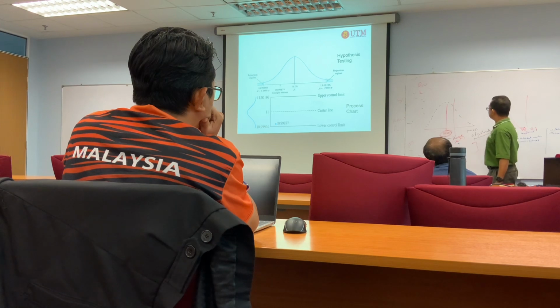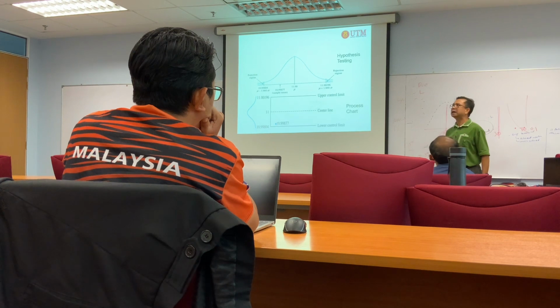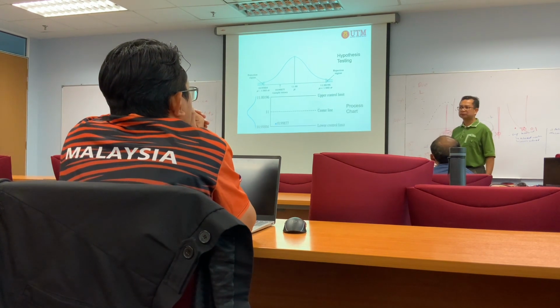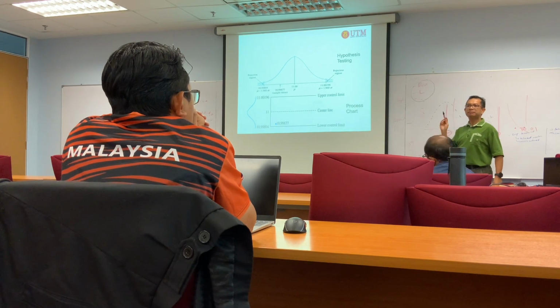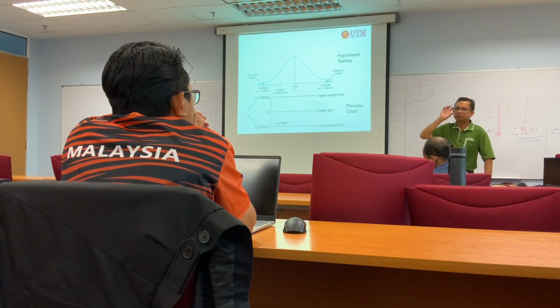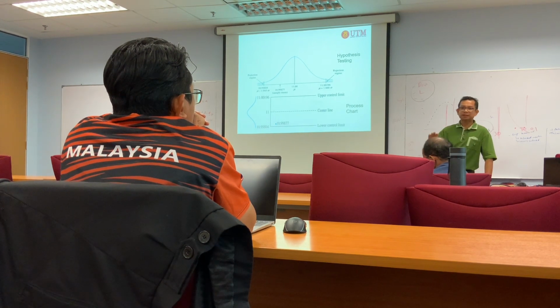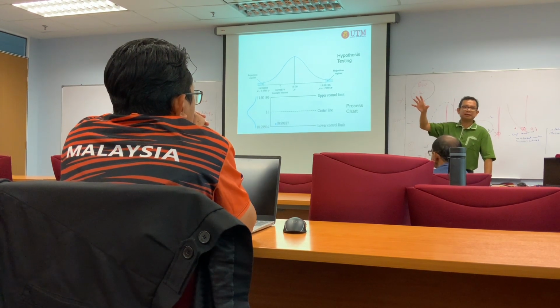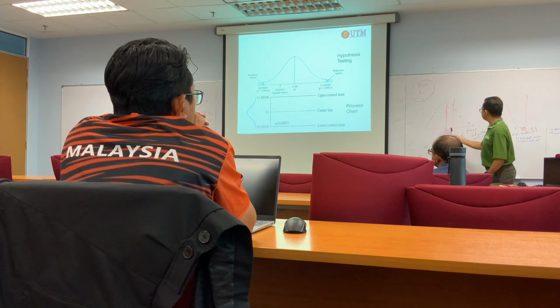Okay, right. When we do the mean adjustment, that's why we need to do statistics as well. In Taguchi, we use signal-to-noise ratio. From there we know which variables are important. In statistics we use ANOVA. So using ANOVA, we also know which variables are really important, highly significant. That's statistics, but in the Taguchi method we call it a high signal-to-noise ratio. So that is highly significant.